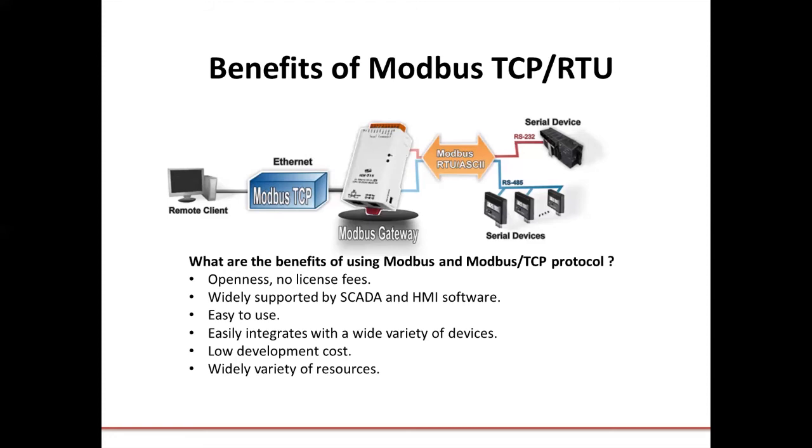There's also Modbus gateways, which can convert Modbus serial data to Modbus TCP data. Modbus RTU and Modbus ASCII are serial based. You need an RS-485 or RS-232 connection. And then Modbus TCP is the Ethernet version of it. So it helps to bridge the gap.